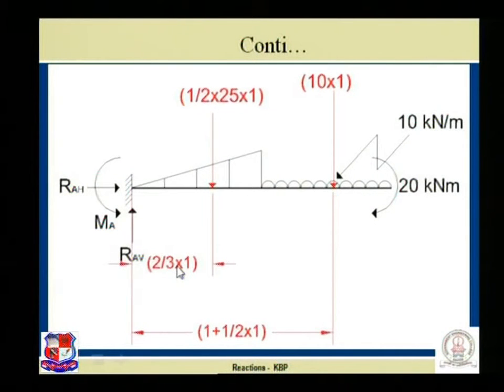This comes for the specific nature of a simply supported beam, where there are two different supports: one is a roller, another is a hinge support. In that case there are two reactions, but vertical reaction is only one, RAV. So when we use sigma V equal to 0, then RAV, which is acting upward, minus UVL minus UDL. There is no effect of this concentrated moment in the calculation of sigma V.